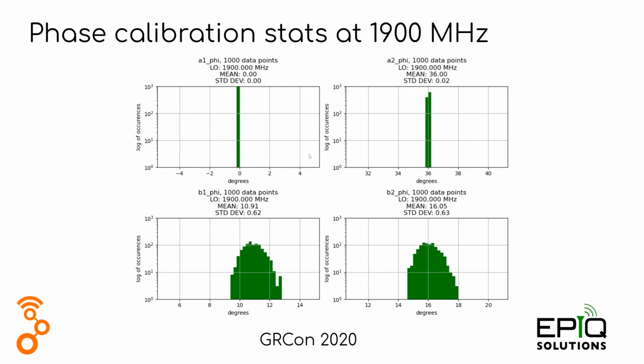And you can definitely tell the difference between chip B, which has the phase synchronization with regard to chip A. These use the same LO actually, and these would use the same LO. These are the channel Bs here. But everything is referenced to channel A1, so naturally channel A2 would be tighter grouped. It's using the same LO, and this is a different LO, and this will show you how well Analog Devices has done their phase synchronization. It's pretty tight.